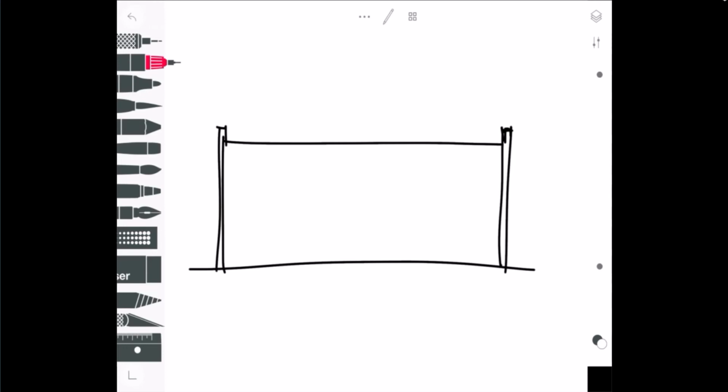Okay, in this video, we're going to look at the process of sloping a roof structure. So now let's just say we have a building like this, and usually the intent or the design approach to sloping roofs for larger commercial buildings is not to slope to the outsides. That's not usually the approach like you'd see in residential. The approach is to slope inwards from the parapets to various roof drains on the building.